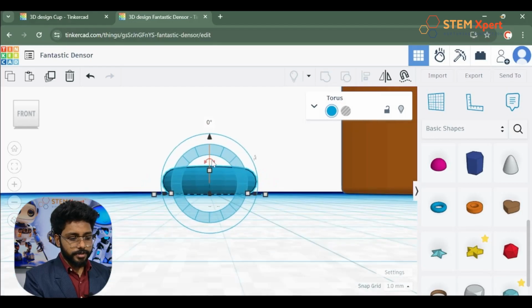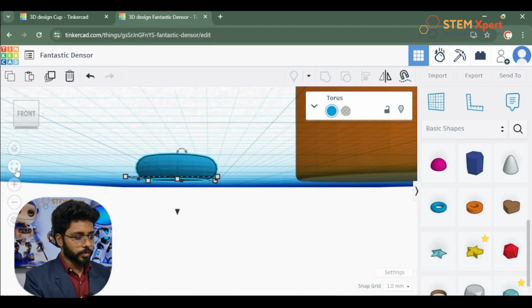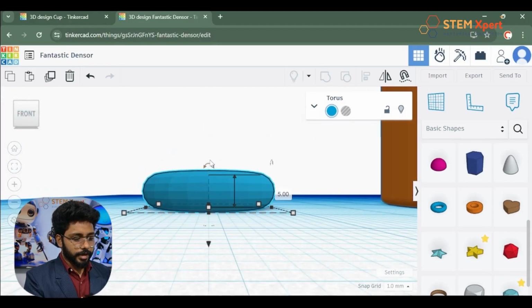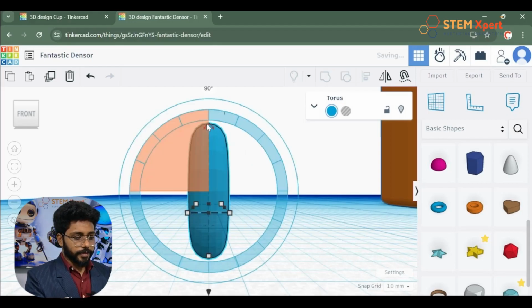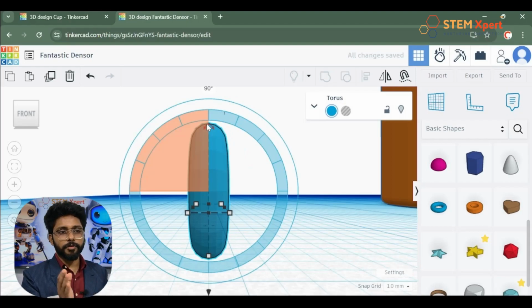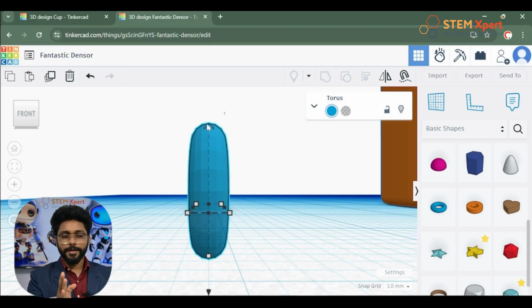So let me share the details of it. If you go to the fit view again, there you can find this arrow, and you can give it as 90. When you give it as 90, it will be rotated and tilted at a 90-degree angle. Can you see it? In the same way, we type the angle that we require.